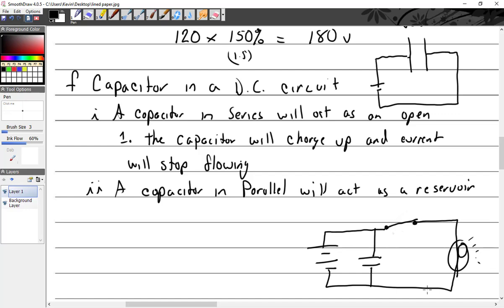If you have enough voltage, usually not from a battery, but some things like magnetos have very high voltages, as you open the switch, when it's just barely opening, it'll arc across and start burning the switch out.